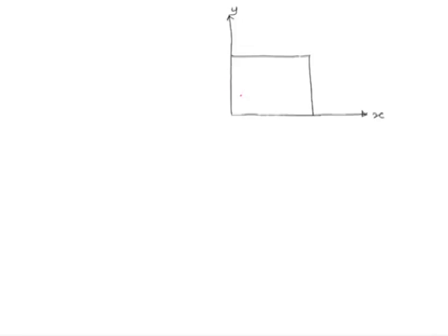At the centroid of the negative x plane, we have the velocity component given by u and rate of mass flux that will be given by rho times u. On the positive x face, here this u has to be obtained from Taylor series expansion, that u at x plus delta x, and similarly this rho u has to be obtained again in terms of Taylor series expansion.